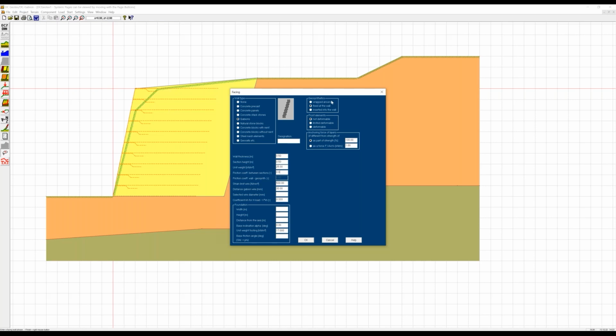Or they may be inserted into the wall, which means that we have some friction between the different blocks. And this would be the coefficient for the friction between walls and geosynthetics. So the load from the different blocks multiplied by the friction coefficient gives the maximum force which can hold the earth pressure on the wall.